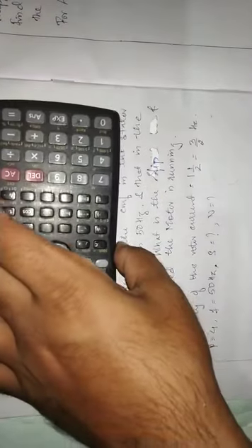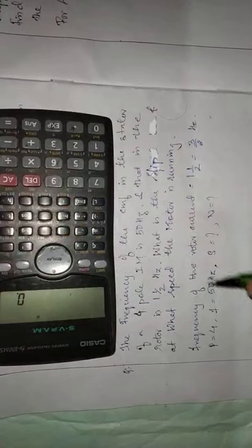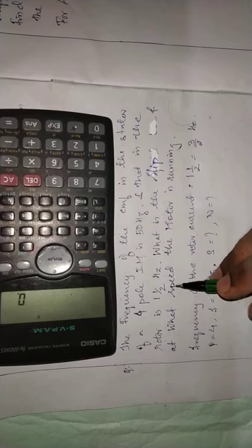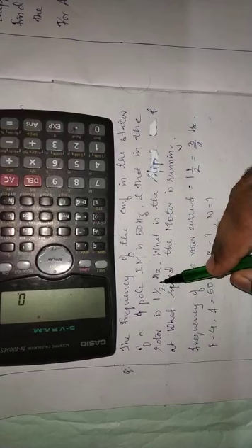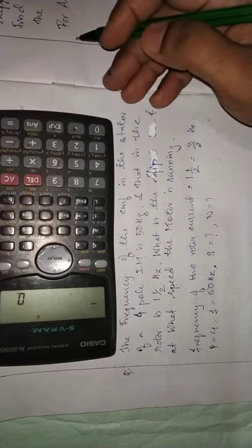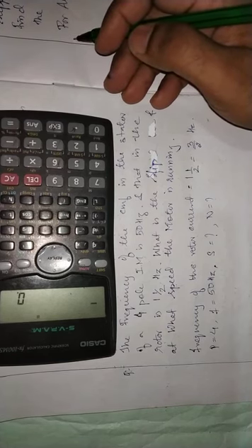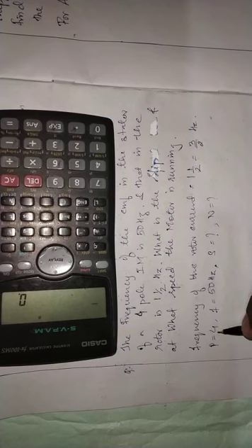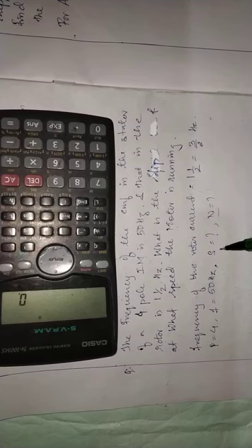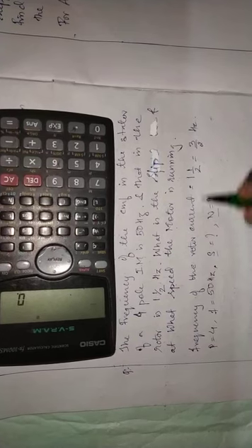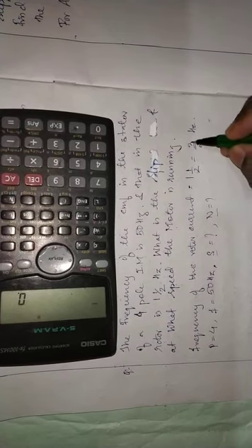Now the frequency of the EMF in the stator of a 4-pole induction motor is 50 Hertz, and that in the rotor is 1.5 Hertz. What is the slip and at what speed is the motor running? That is the question. Now we need to find the slip and at what speed the motor is running, that is the value of N of the rotor and slip of the induction motor. Frequency of the rotor current is 1.5, so it can be written as 3/2 Hertz.